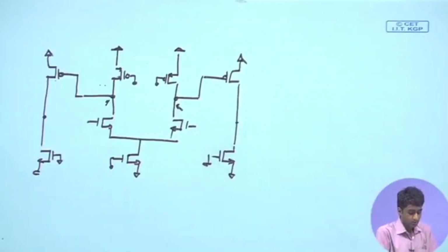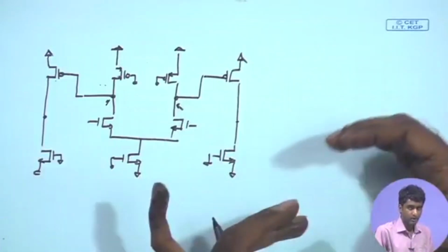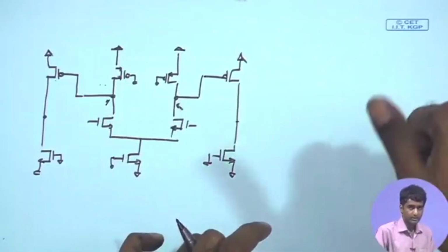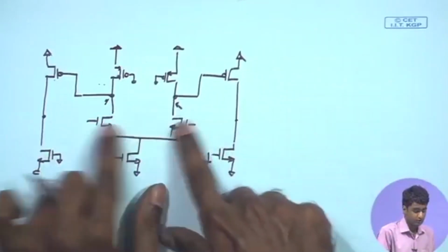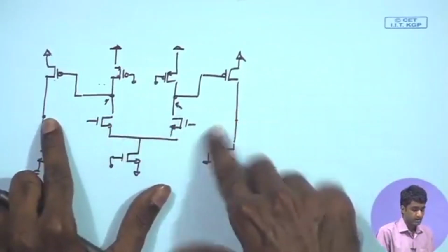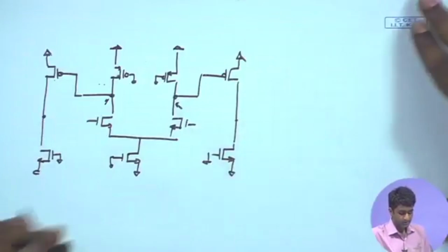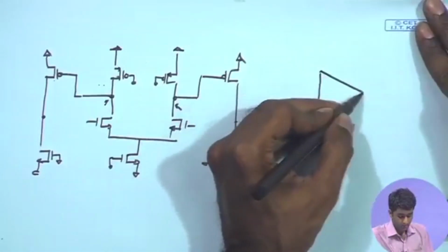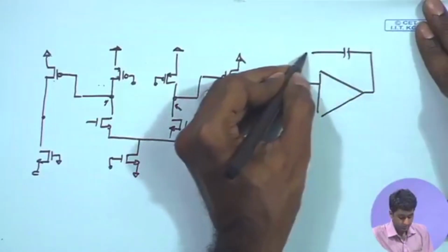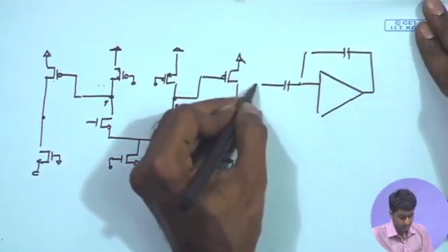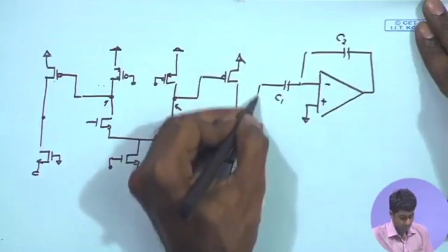So, we also looked at the feedback operation that we are applying over here. So, we need to look at the block level also, how those feedback elements can come into picture to determine the overall loop gain. So, this is giving you the open loop gain of the standalone amplifier. We need to incorporate the loop gain coming because of the feedback operation. So, let us go back to the block level description of our feedback amplifier. Again, I am reverting to the single ended topology just for simplicity of the analysis, and let me call this C1, C2, and you have the input signal over here.